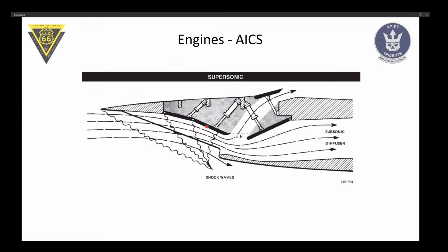This is a pretty complicated arrangement, and not many aircraft have this, even fighter aircraft. There are also many aircraft with a static inlet setup, such as the F-16 and F-18. So technically, you can have some static geometry that does a one-size-fits-all approach. Whatever your Mach number, it's going to accelerate your flow to subsonic speed. However, it will do that inefficiently. The stronger your shock becomes, the more energy it takes out of your flow. And ideally, what you want is an infinite number of infinitely weak shocks, and weak means that the change in Mach number is infinitely small.